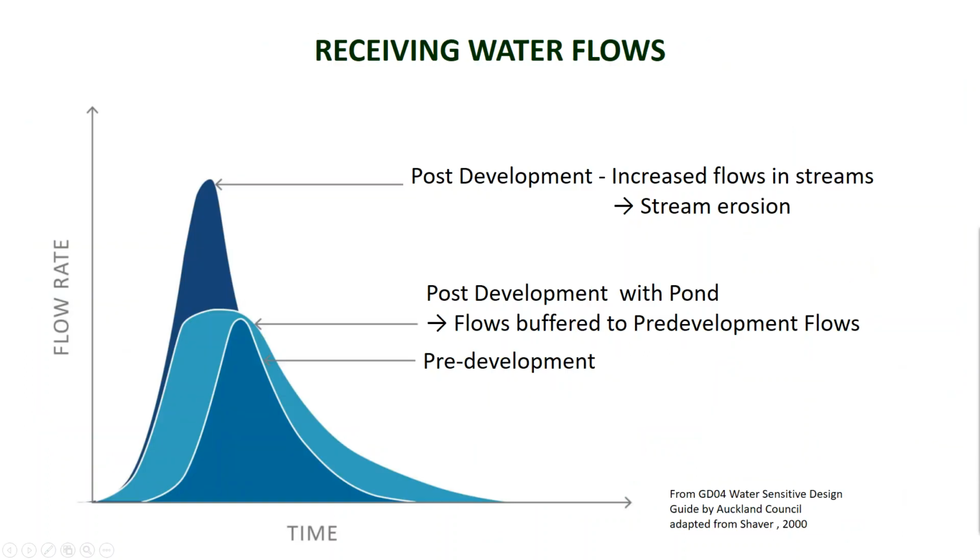And that's what's shown here in this video. So there is our traditional system. There is what things were before. And this is what happens when we put a water sensitive system in. The flows are buffered to match those of the pre-development as well. That's called hydraulic neutrality.